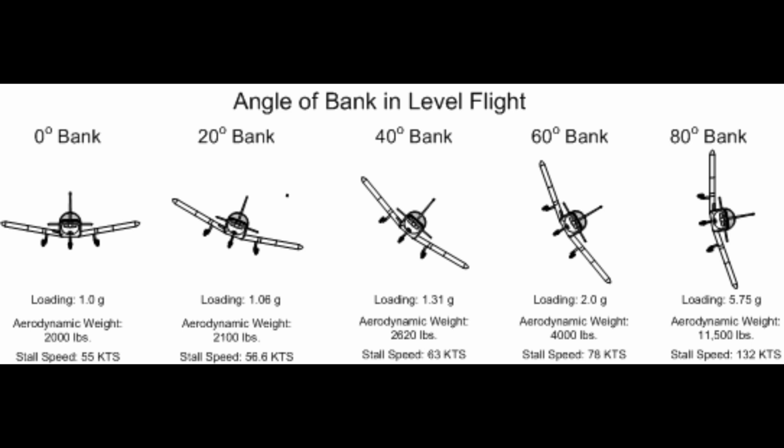However, such extremely abnormal loads must be dismissed somewhat if aircraft are built that take off quickly, land slowly, and carry worthwhile payloads. The problem of load factors in aircraft design becomes how to determine the highest load factors that can be expected in normal operation under various operational situations. These load factors are called limit load factors. For reasons of safety, it is required that the aircraft be designed to withstand these load factors without any structural damage.